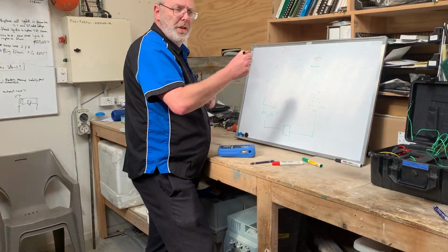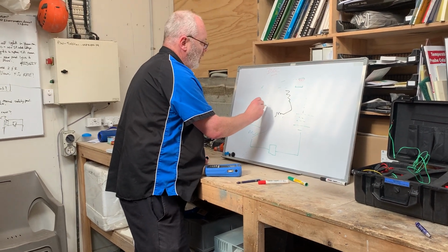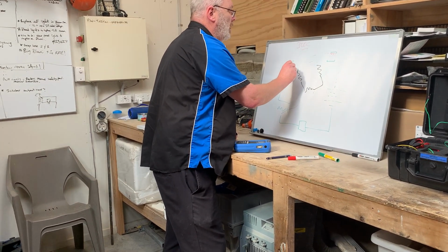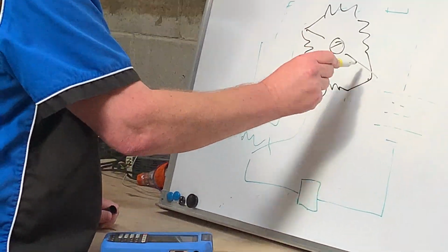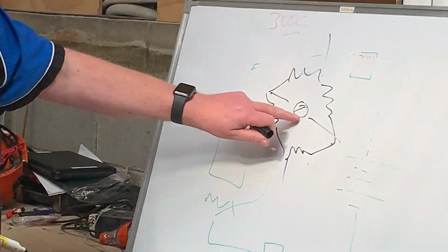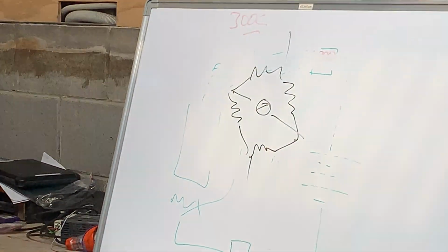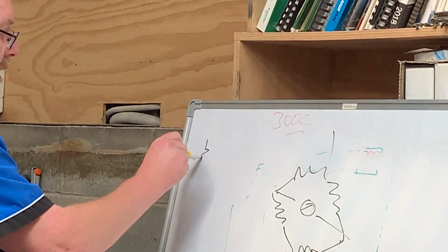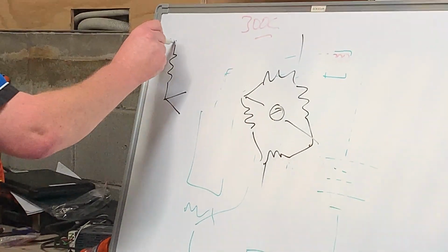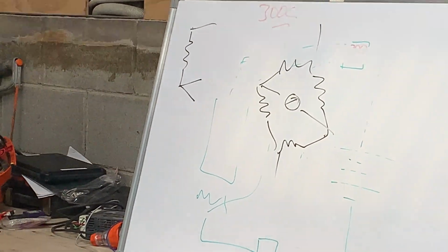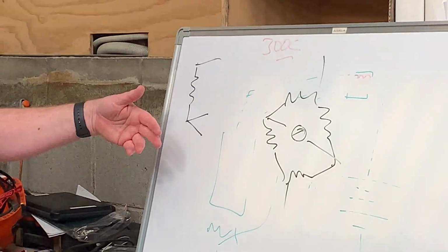You know what a Wheatstone bridge is? Yeah. So you've got your 4 resistors. I'm the worst artist in the world. Yeah, there we go. If we put a voltmeter across there and we put the voltage in here and here, we get 0 when all these are equal. With a 3-wire RTD, you'll notice that the RTD is a resistor. You've got 2 leads off one end and 1 lead off the other. People think, well, that makes no sense because they're in parallel. Why don't we just use 1 wire?